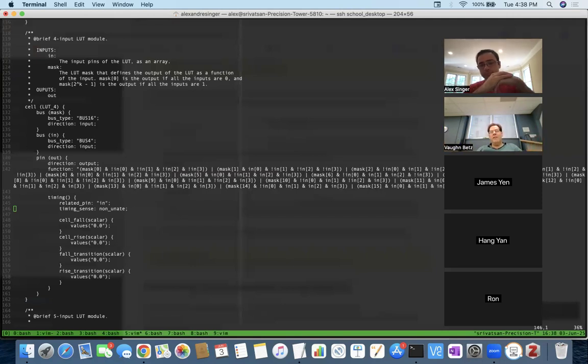And then you can feed that to the next cell. If that next cell is also unate, but now it turns out that a rising input produces an output in 120 picoseconds and a falling produces a falling in 100 picoseconds, you add those together and you get, no matter what, 220. And if you had done the worst case of just taking the max delay on each one of those cells, you would have gotten 240.